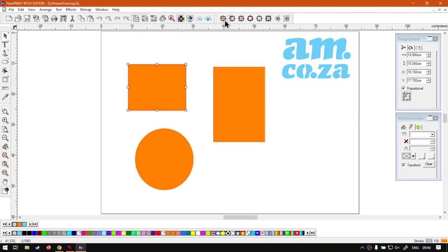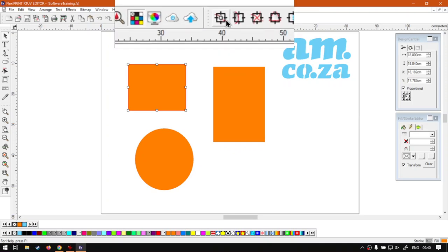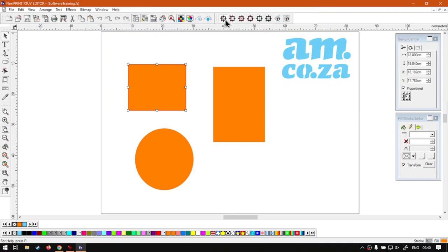We're going to start with the first one, which is point. Now the point is pretty much a node point. So anything that's got nodes, like vector shapes, is going to have points. This thing at the moment has 4 points over here. If I select our draw tool or the curve tool and click, I'll make a single point. So you guys can see that as well. Let me zoom in so you can see there is a point. So I've got a single point here.